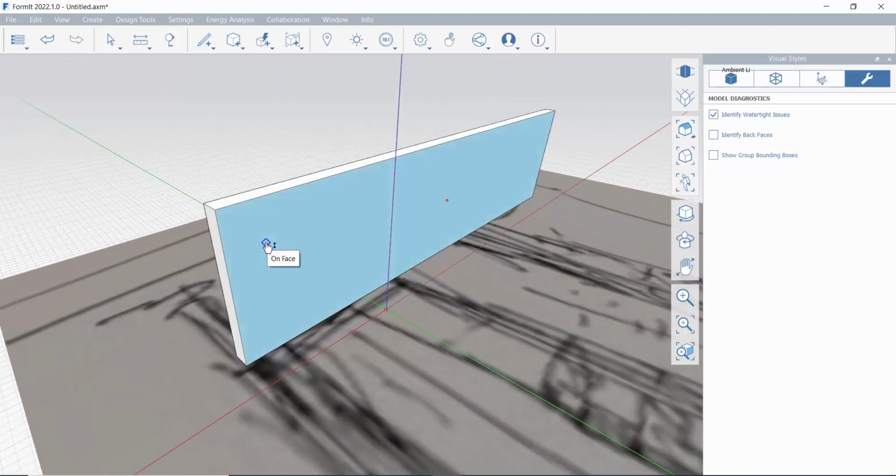But if I were to select and delete one face, big, glaring, red warning sign. Because this is no longer a six-sided object that has an inside and out. It is now 5 planes that are forming a box-like something. So for this project, you want to work with that on. So that if you see red lines popping up, you can go, oh crap, undo, undo, undo, until you get back to no red lines on your screen.